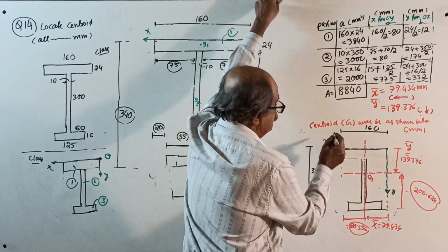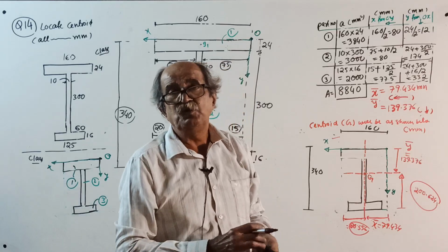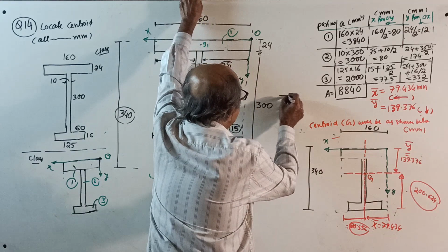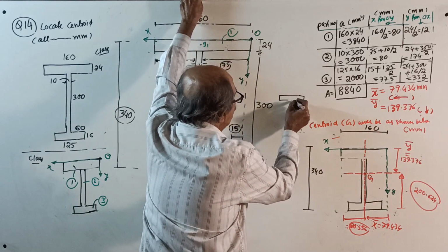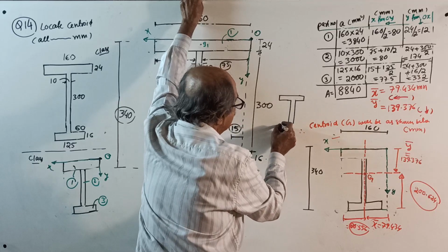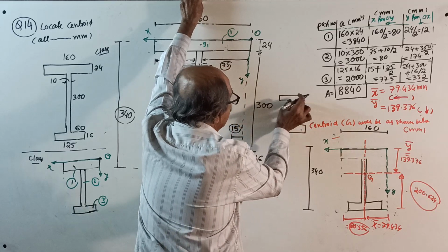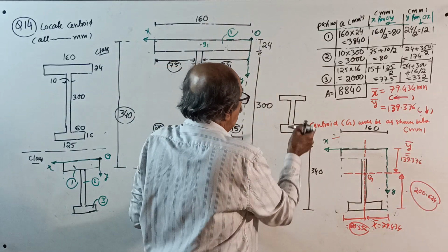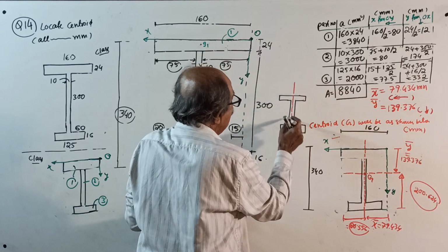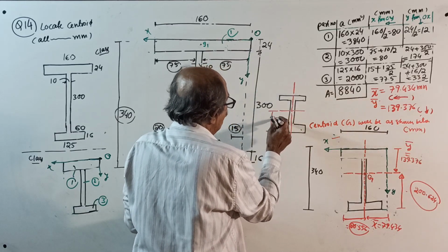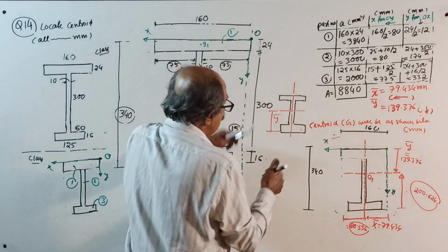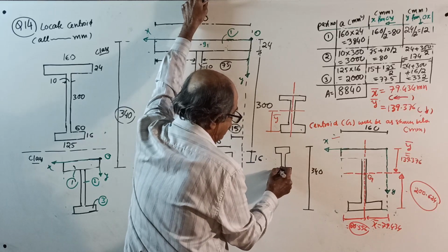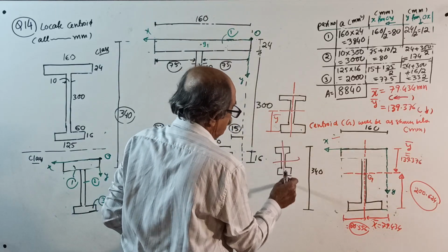Okay. Question is over. I first thought in today's class only, let me do I section. See, most important is I section, unsymmetrical this way. Of course, see, these are equal, these are equal. Then y symmetry is there. Only x you require, means you require only y bar. One more is perfectly symmetrical I section. Then both are equal flanges, nothing required, x, y.